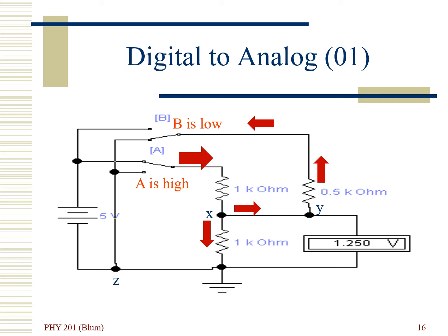On the other side of the half kilo ohm, there is a wire that goes through switch B and then down to node Z. And on the lower end of the lower 1 kilo ohm resistor, there is a direct wire connection to Z. There's a wire connection on one side, XY, and there's a wire connection on the other side. Both of them connect ultimately to Z. And so they are in parallel. So let's look at that.